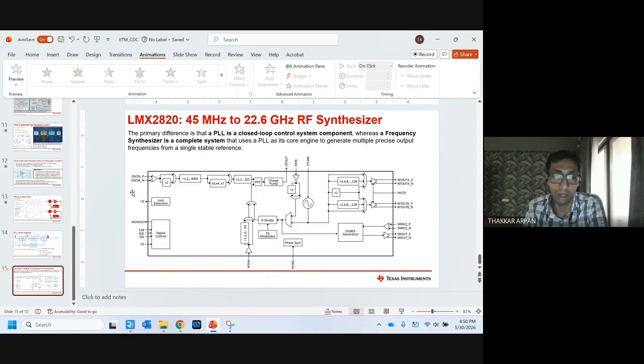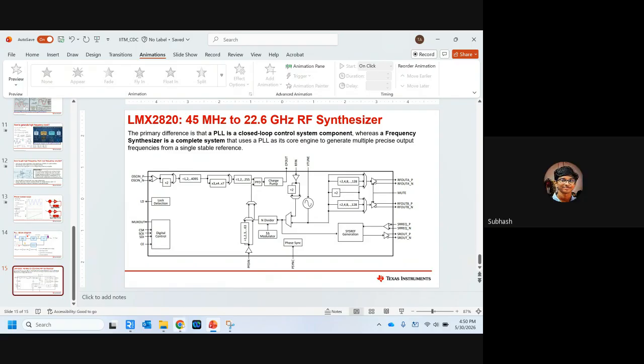Crystal is having a much cleaner stability, and that is why we cannot have our discrete circuit at the input and then generate any frequency at the output. But if your application says that I'm okay with 10 gigahertz also and 9.9 gigahertz also, even if it varies, it doesn't matter to me, yes, in that case, you can use your low frequency source as well. Nobody can stop you in that. It just depends on the application. Does that answer your question? Yes, sir. Got it, sir.